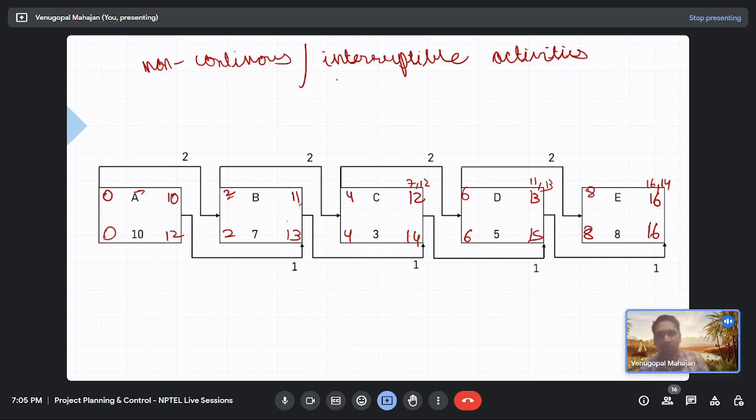Okay. So total float, you know how to calculate total float, right? Yes, sir. So what is total float? Late finish minus early finish, or late finish minus early start minus duration, right? Right now you know that splitting is allowed, so early start plus duration is not equal to early finish, right?